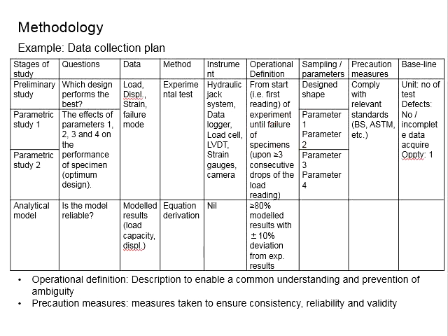Now, how do you know that the specimen has failed? There should be a clear definition of failure of the specimen, which you can observe from the readings of the load cell. You see at least 3 consecutive drops of the loads reading as given by the data logger. Then you know that the specimen has failed and the load resistance of the specimen cannot reach higher than what